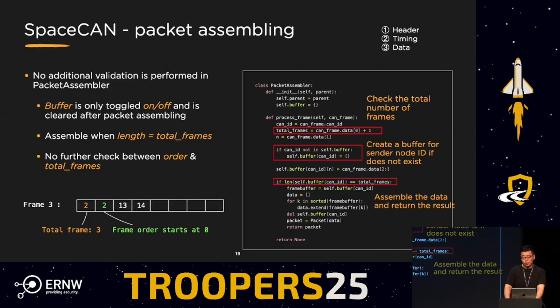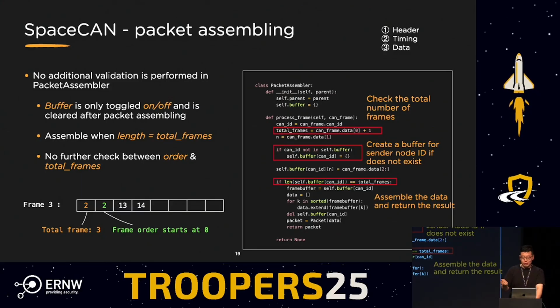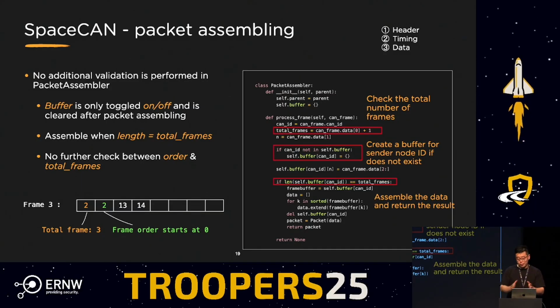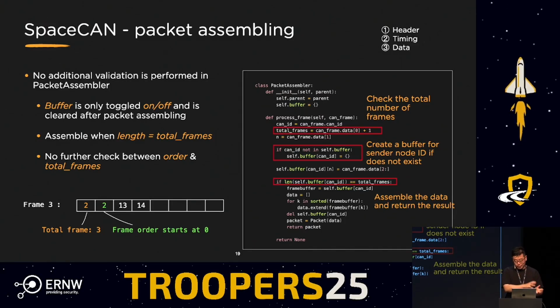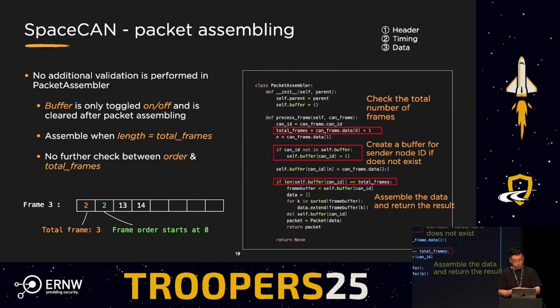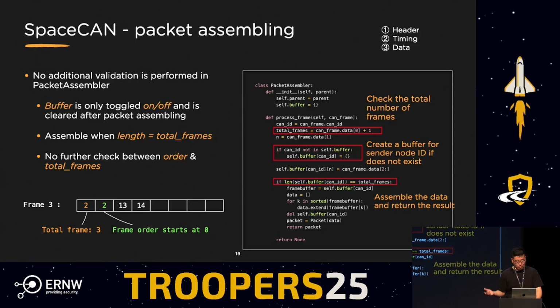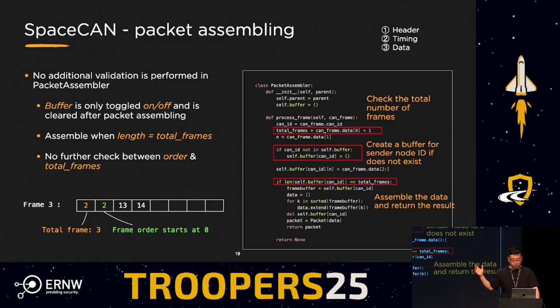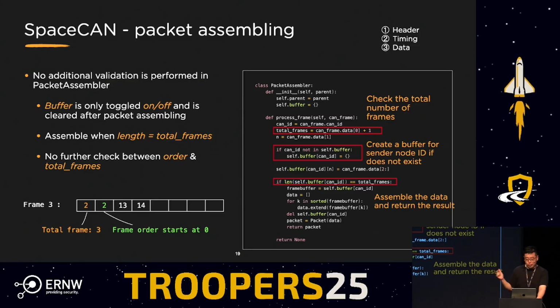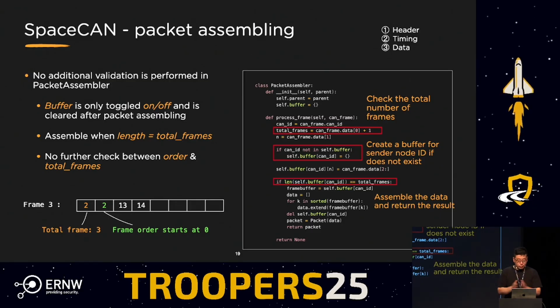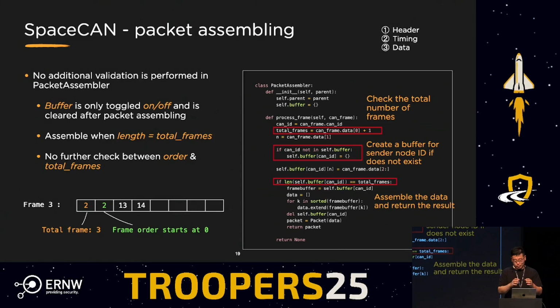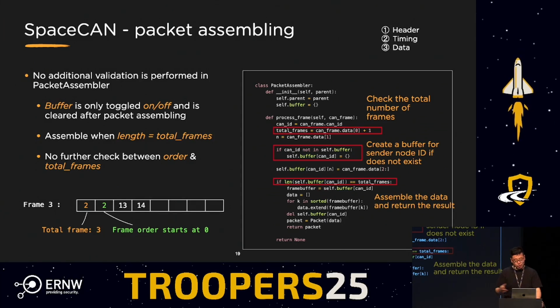And after the controller receives the multiple frames from the split, or you can say separate packets, you'll start to assemble. How they assemble it is by the logic on your right-hand side. Firstly, you will check the total frame, which is actually the first reserved byte.